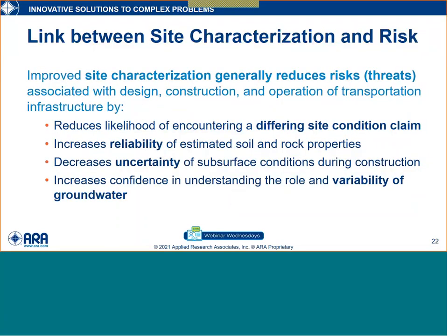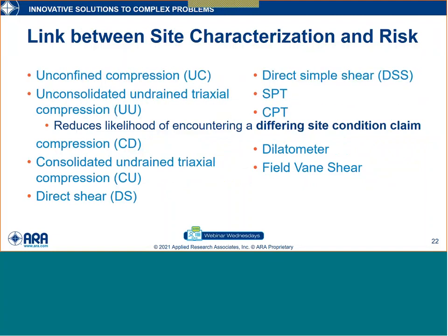So kind of to close this section out, what's the link between site characterization importance and risk? And there's no free lunch here. So if you're going to expend more effort, and I use the term effort, that could be resources by money or staff time, what you're trying to do is actually reduce threats, reduce the risk, and increase certainty. And if you look at the 4 bullets on this slide, they speak to more specific benefits of an adequate site characterization. There's an enormous amount of information that's available from FHWA, the Corps of Engineers, AASHTO, just to name a few, that addresses this topic.